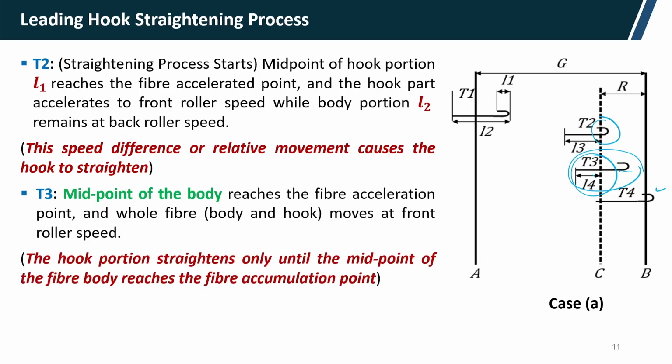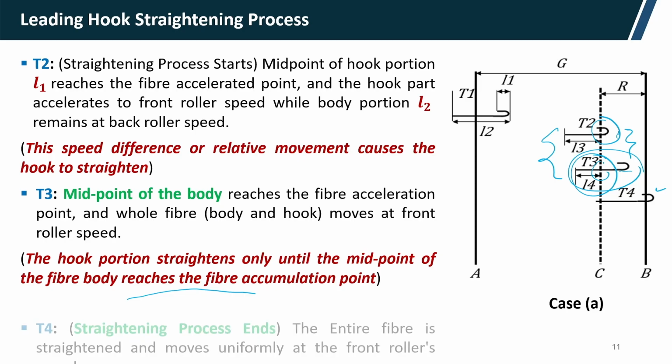The hook portion is straightened only until the midpoint of the body reaches the accelerating point. So, from T2 to T3 the hook removal takes place. That means the longer this distance, the better the leading hook removal will be.